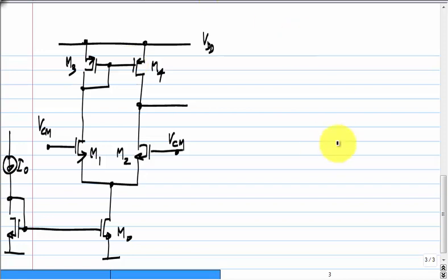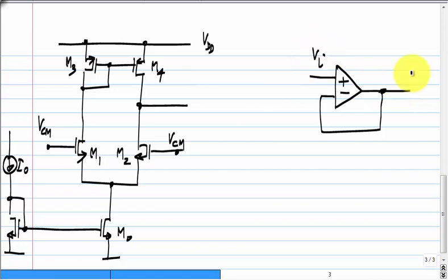Okay. So, an example of how we use it is that. We place some feedback, and for now I will take unity feedback. What kind of a circuit is this? This is just a buffer, right? So, ideally V naught should be simply equal to V I. So, what should I connect to what? This is the plus terminal of the op amp, this is the minus, and this is the output. So, I have to connect the output to the minus terminal.